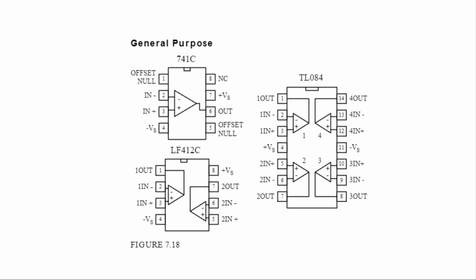Now for the different kinds of op amps, the first kind is general purpose op amps. There's a huge selection of op amps out there. Unlike general purpose, precision op amps are designed for high stability, and you'll find op amps that fall into one of the following categories based on their input circuitry. There's bipolar, JFET, MOSFET, and some hybrids thereof, like BiFET, which is bipolar in one of the FETs. In general, bipolar amps have higher input bias currents than either JFET or MOSFET, and this means that their input terminals have a greater tendency to leak current.